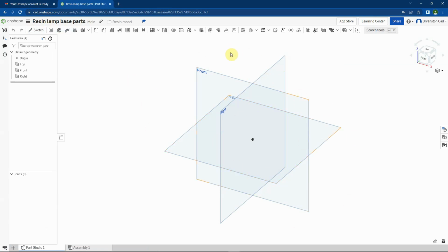I've actually got what are called 3 different work planes. The work planes you can think of as being pieces of paper or pieces of glass, if you like, because you can see through them, that you can draw on. So they're flat surfaces for drawing on. We have a front one, and as I hover over it, you can see that it highlights the edges in orange. A right one, and again, as I hover over it, it highlights the edges in orange. And a top one. Every time you create a new model in Onshape, it starts with these 3 default work planes. So if you like, 3 pieces of paper that you can draw a sketch on. Once you've created a sketch, you can apply a feature to that sketch to turn it into 3D. Now, if that sounds a little bit confusing, I'll show you how to do that in a moment.